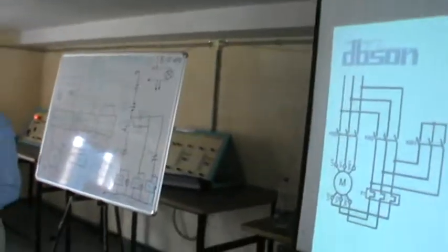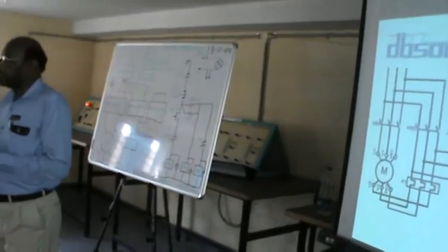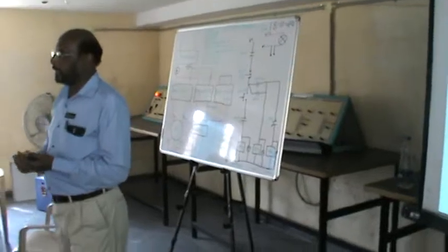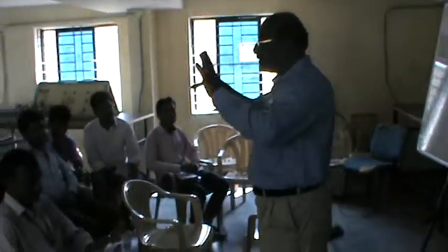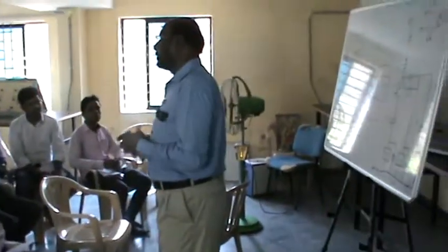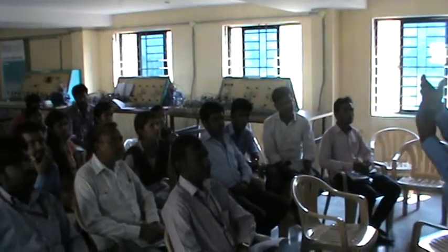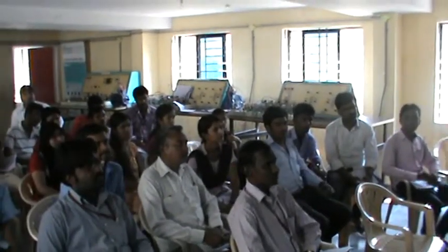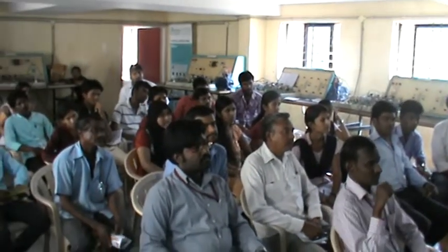Selection is very, very important. Which contactor? For example, for a 10 HP motor, which is the main contactor, which is the star contactor, which is the delta contactor. So NO, overload, all those things you have to select. After that I will give you the selection chart. Afterwards you can do that. So these are the basic circuits used in any industry. For example, in your Gulbarga also, you go to any industry, these are the ready circuits you will find.